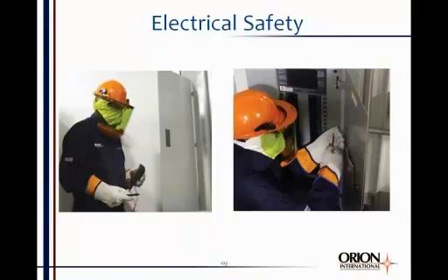Okay, here's some more pictures of guys going to work in electrical equipment. Again, this fellow's wearing an arc-rated balaclava or sock hood to protect the back of his head. He has the face shield, safety glasses, earplugs. Why earplugs? To protect your ears from bursting if an arc flash were to occur. The pressure wave is so great from an arc flash that your eardrums will burst.